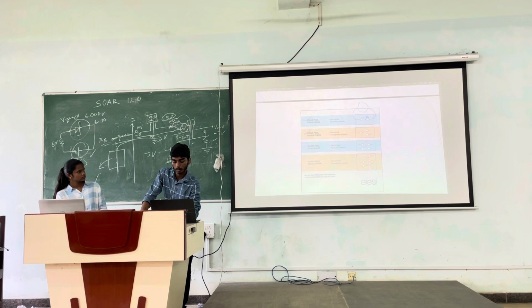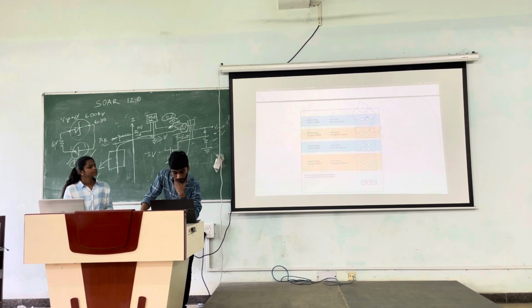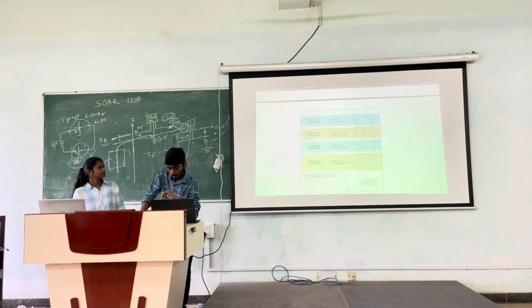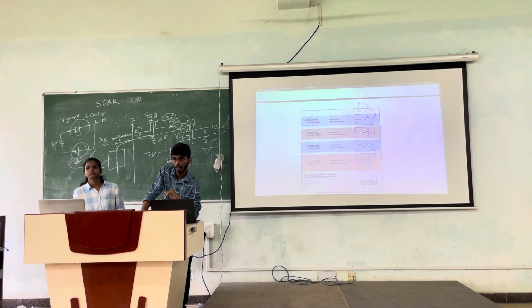Now single pole, double throw. In this switch, we are still having one terminal on that side, so we can control one circuitry using this port. Okay, and we have two contact points, like this toggle. Once it is attached to the top position, it is connected to this point, and when it comes down, it will be connected to this second point. Okay, so we have two contact points and one port for our circuitry. So that's why it is single pole, double throw.